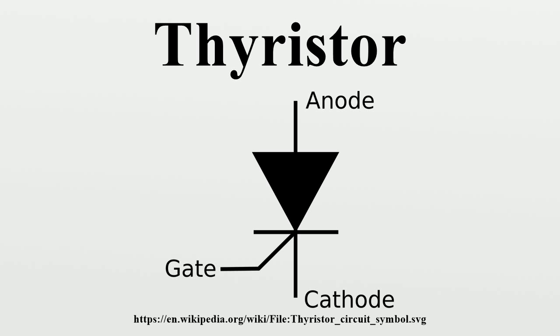Reverse conducting thyristor. A reverse conducting thyristor has an integrated reverse diode, so is not capable of reverse blocking. These devices are advantageous where a reverse or freewheel diode must be used. Because the SCR and diode never conduct at the same time, they do not produce heat simultaneously and can easily be integrated and cooled together. Reverse conducting thyristors are often used in frequency changers and inverters.